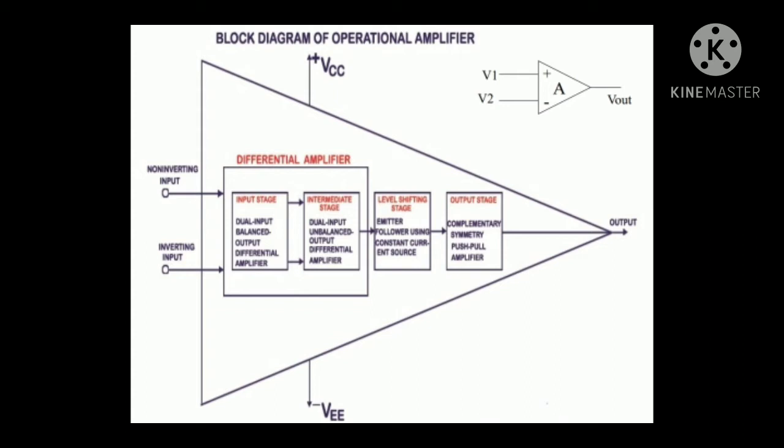The first stage is a differential amplifier, which is a dual input balanced output differential amplifier. It means it has two inputs and two outputs. It decides the input impedance and is called the input stage.